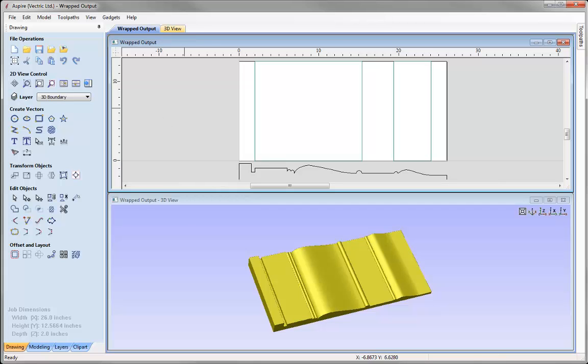The Vector Unwrapper requires me to draw a vector which represents the cross section as I want to see the object once it's been wrapped. So to create a box in the wrapped environment, I need to draw a square and then use it to unwrap that to give me the vector that I can sweep in the 3-axis environment to give me the right shape. So to help me get these shapes, I'm going to do a bit more measurement on my profile.